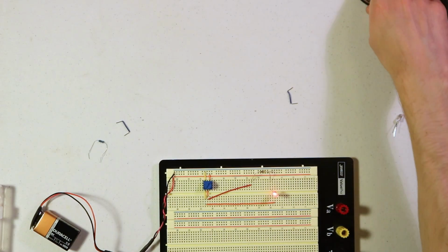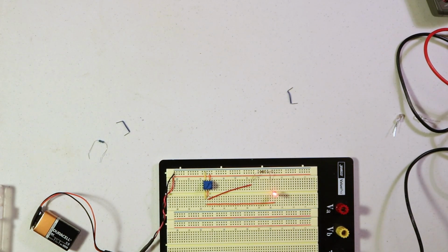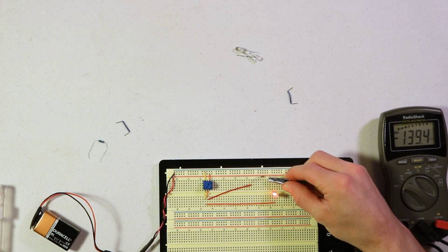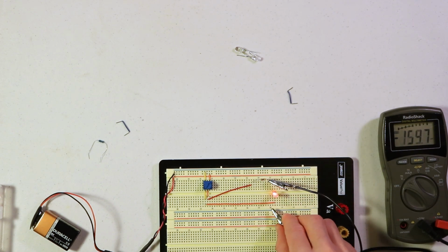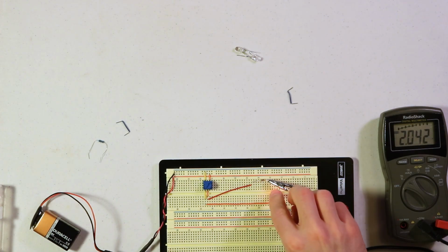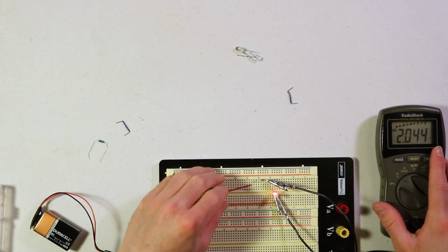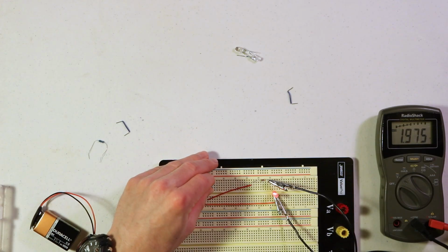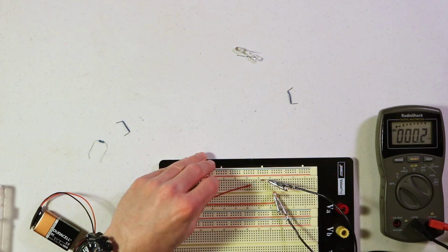And now let's check our voltage and current across the LED as we change it. So again, let's use our alligator wires, and I'm just going to clip this to the end of the resistor. That's also connected to the end of the LED. And then I'm going to clip the other end to the side of the LED, and we can see now that we've got 2.044 volts. So now let's just watch that voltage as I adjust it up and down. So you can see that it's being applied.